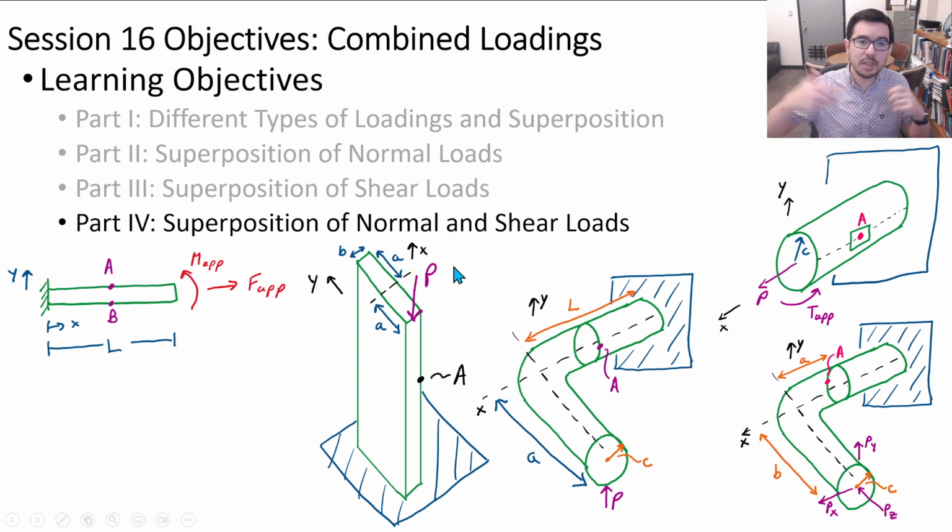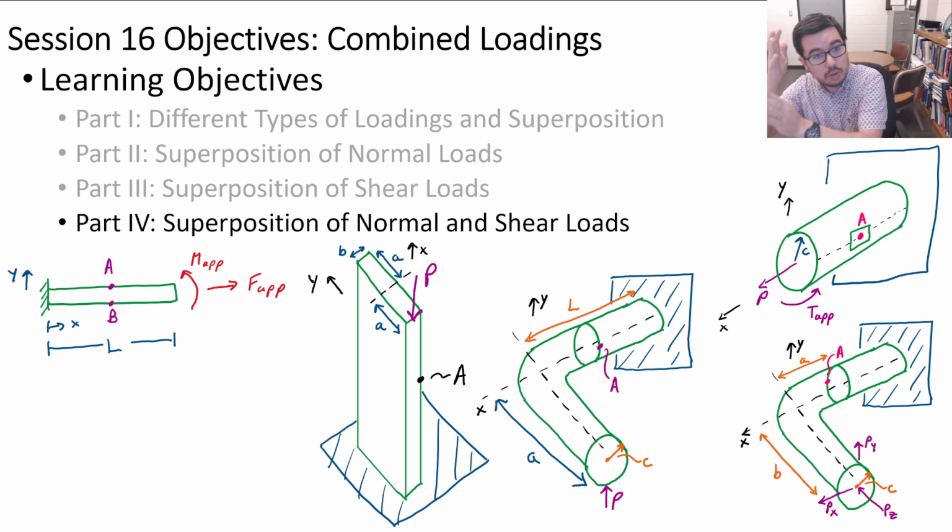or normal and shear stress doesn't mean we can add a normal stress and a shear stress to each other, right? But we can add normal stresses to each other, and we can add shear stresses to each other, okay, and then put them on an element. Later we will look at how we can do transformations, and there can be equivalent normal stresses due to shear stresses and vice versa.